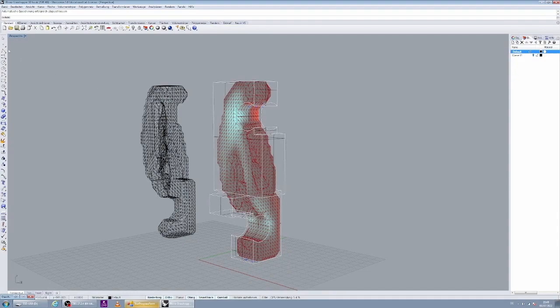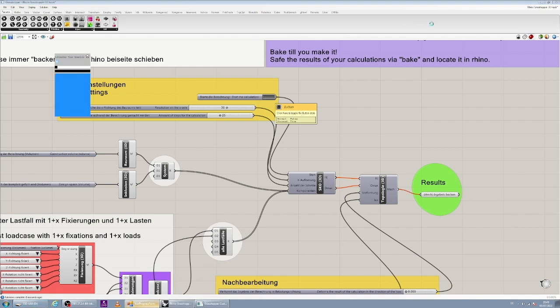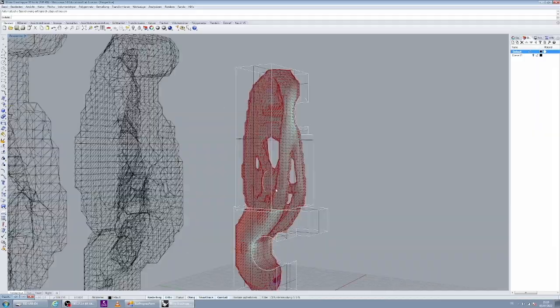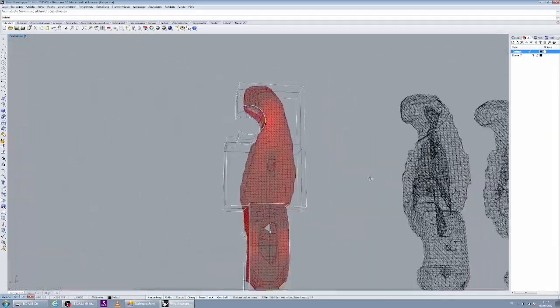If you have problems with getting results, try to go from less complex calculations to more complex ones to get solid results. Check if the steps are set too high or too low and try out different settings. Keep in mind that the steps are the amount of pixel in the x-axis. Another thing you can try is to make the construction space larger in the 3D calculation.